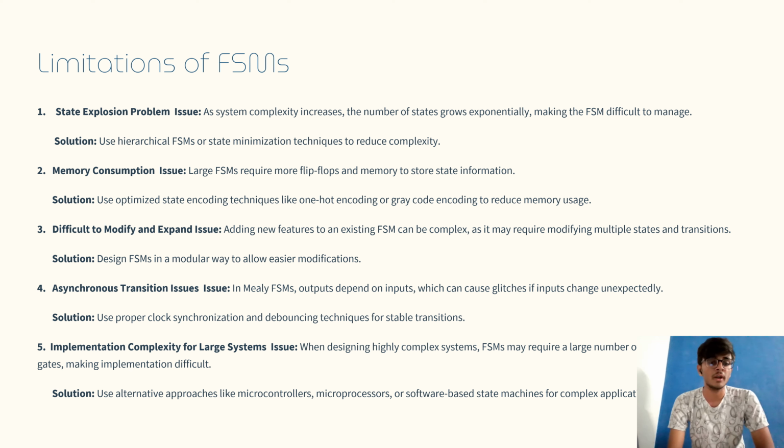Third is difficult to modify and expand issue. Adding new features to an existing FSM can be complex as it may require modifying multiple states and transitions. And its solution is design FSM in a modular way to allow easier modification. Fourth is asynchronous transition issue. In Mealy FSM, output depends on inputs, which can cause glitches if inputs change unexpectedly.